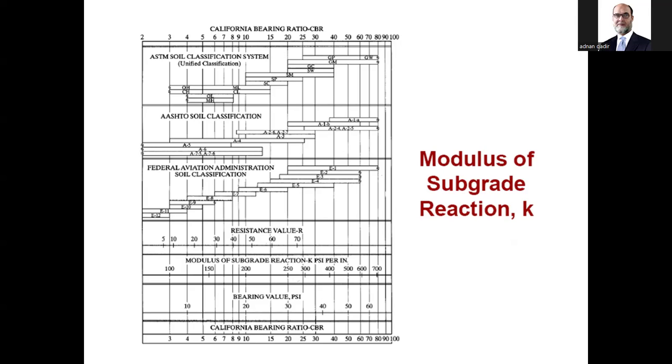So if you don't know the CBR value, what do you do? If someone has not tested the ton per square foot value, because most of the time this is a practice in our industry that people don't even do this test. They assume, oh, previously I have designed foundations at 0.5 ton per square feet. Every time you will hear me talking about 0.5 ton per square feet, because people have assumed in Karachi that it is the normal value. So based on their assumptions, even though they don't do the test, they come up with this value.